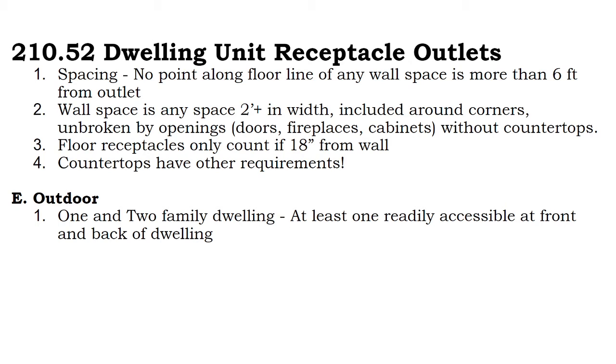Whereas on the low end of things, the 15 amp, 20 amp, you have a lot more fudge factor or intentional wiggle room in that outlet. There's spacings for receptacles. This general home building knowledge, we're not going to get into in as much detail and will just leave it to you to read through after class. Outdoor outlets, there's a requirement now to have outdoor readily accessible power at the front and back of dwellings.